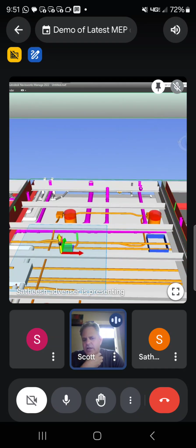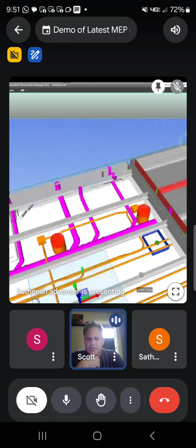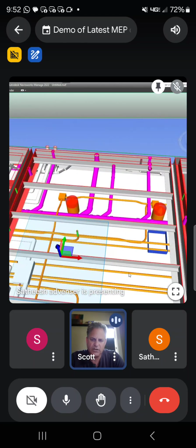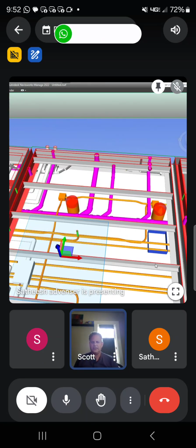I had that question right off the get-go: we need to have 4-inch clear space through that. If we were to run the joists in one little section the other way, then we could use the joist cavity to get that out of there.